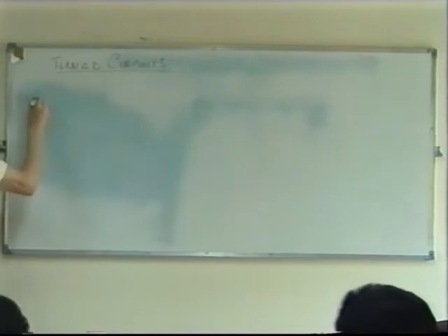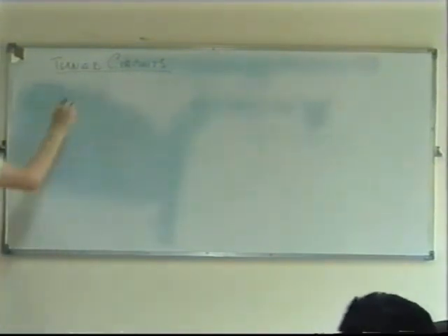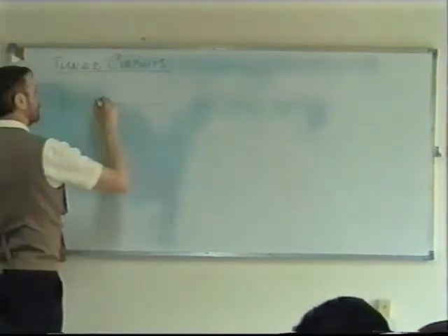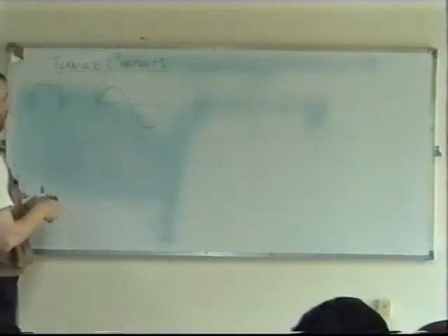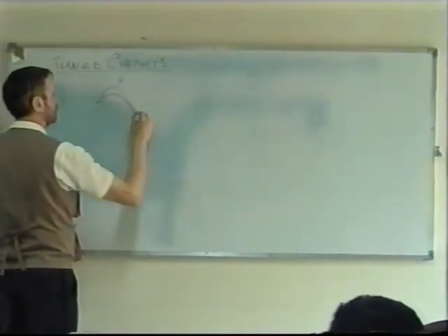We're going back now to talking about resistors, capacitors and inductors. If I have an alternating supply and I connect that across a resistor, I can draw a diagram showing the current through the resistor and the voltage across it. The voltage across it I can represent as a sine wave. Do you agree with that? An alternating voltage, an alternating sine wave. And I can show the current through it also as a sine wave. And notice here, the bigger the voltage, the bigger the current.